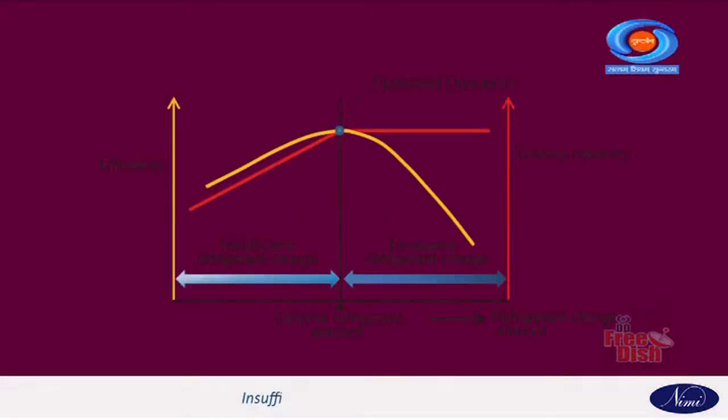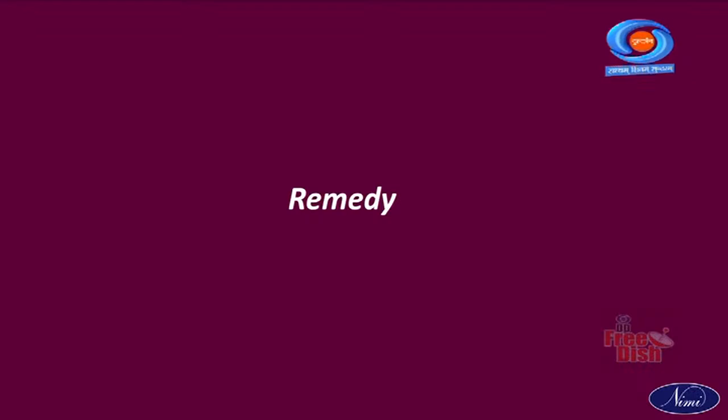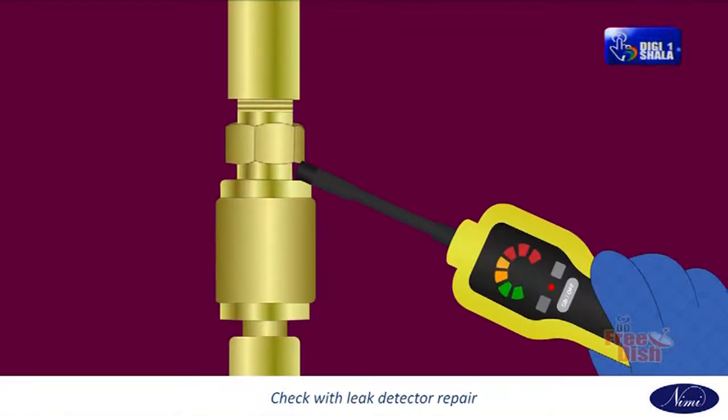Diagnosis: insufficient refrigerant in the system. Refrigerant leaking. Remedy: check with a leak detector and repair. Charge refrigerant to proper amount.